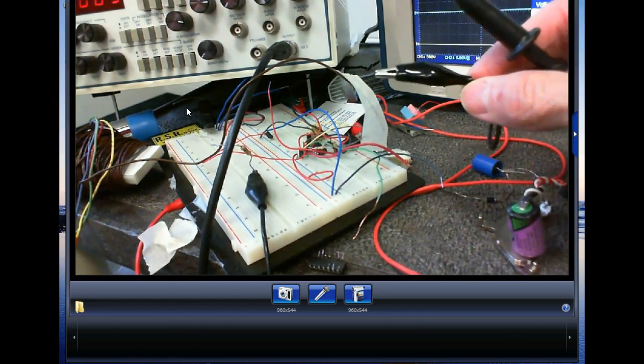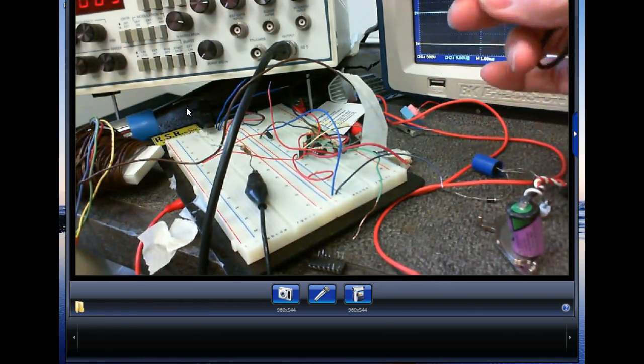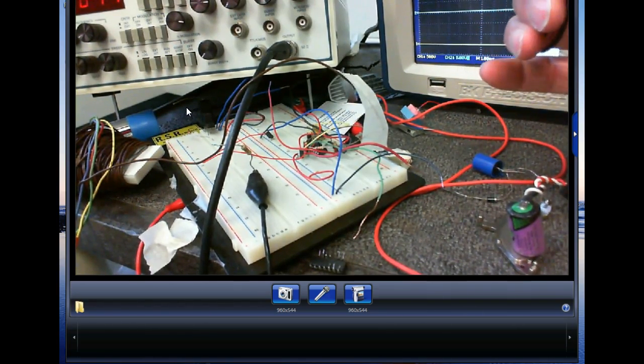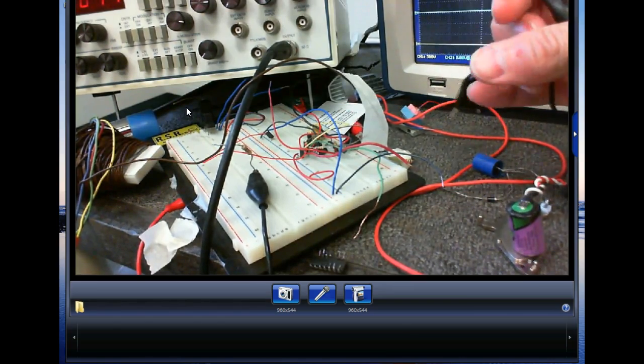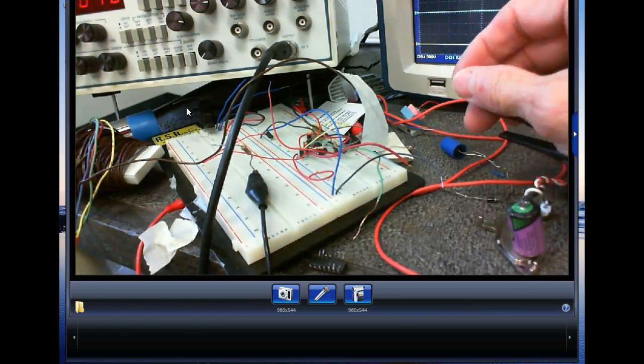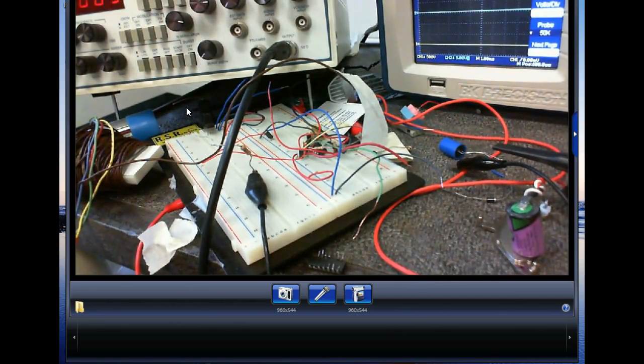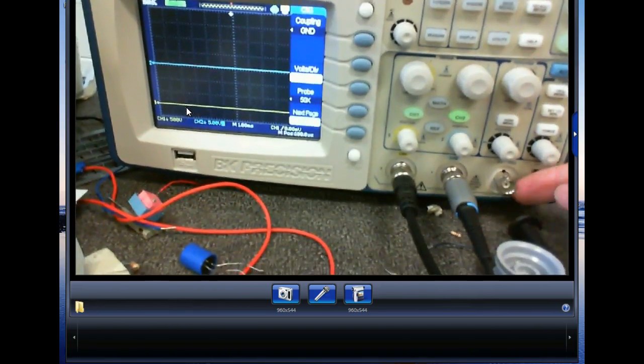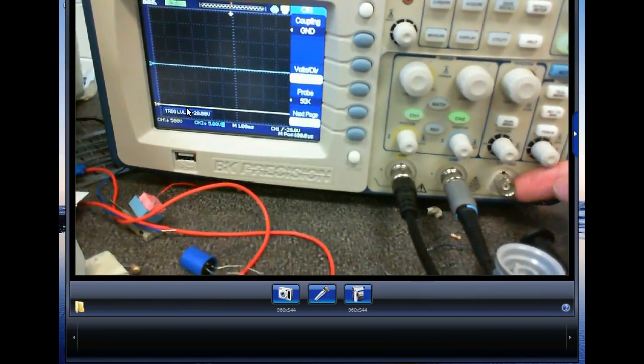An oscilloscope, this right here, is connected to earth ground through the power plug. And out at US Steel, they have what they call isolation transformers that you can buy for an oscilloscope. You can plug it into the wall and plug your scope into that, and what it does is disconnect the ground from the oscilloscope. Now, the big problem you have there is that you can put that black lead anywhere in the circuit, but all these little old metal things take the polarity of whatever you use the ground to.